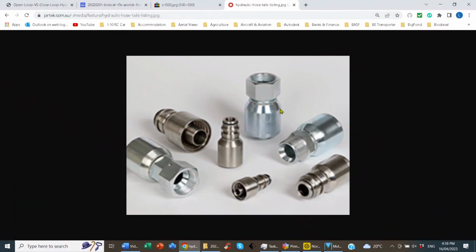Now, what's involved in a hose? The rubber bit, except it's not just rubber. There's a lot of reinforcement. There's different ratings, different types. It's braided hose, and so forth. But generally speaking, for hydraulics, certainly, there's a hose end on each piece of hose. So let's look at a few of those. This is just a selection of hose ends.